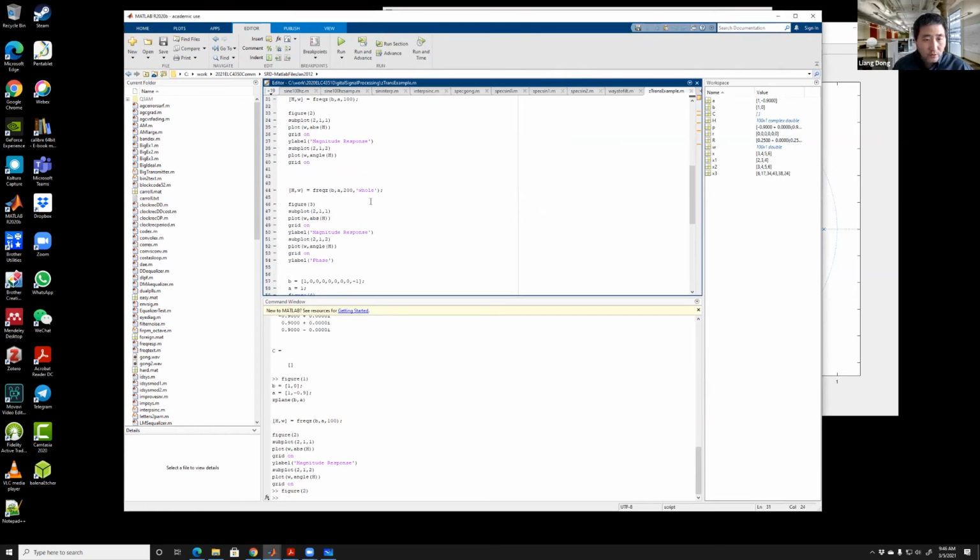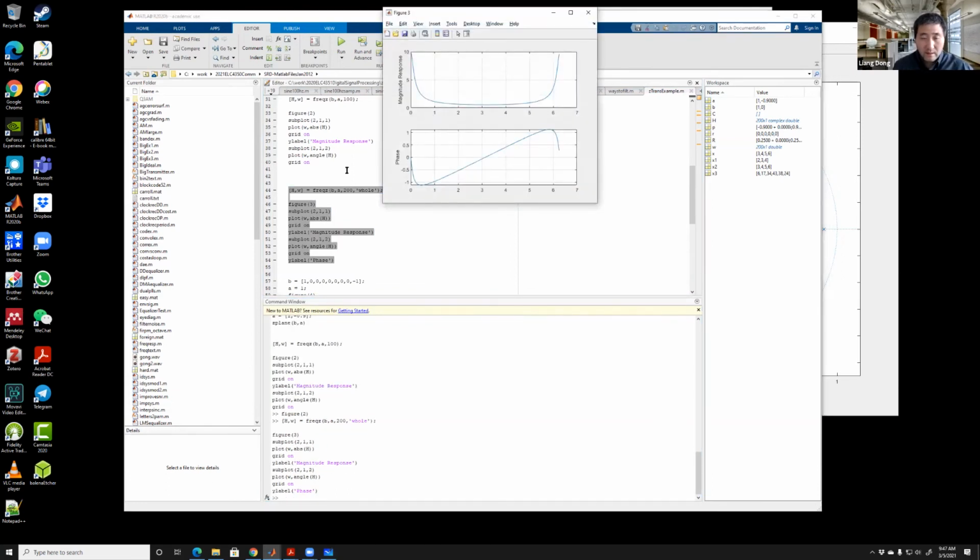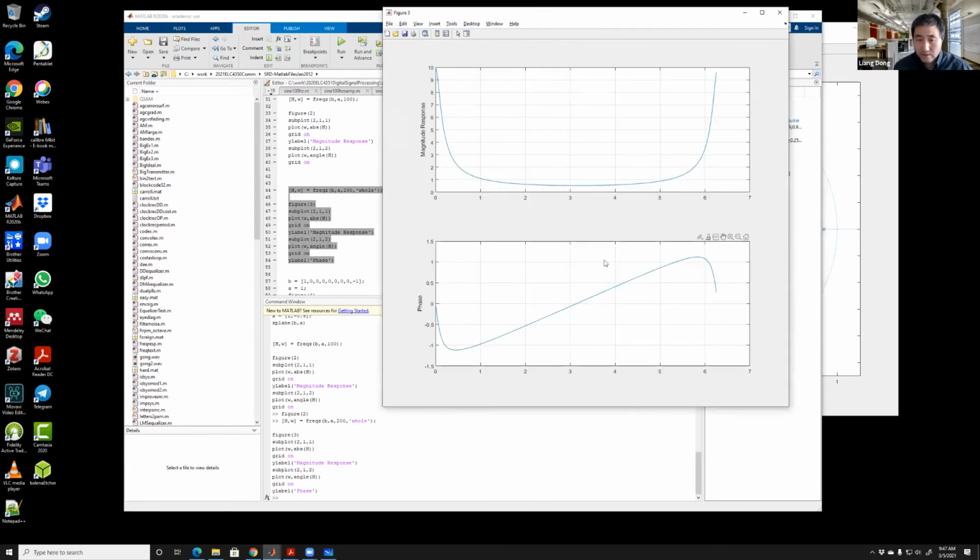Now, if I'm going to draw the frequency spectrum of the entire range from 0 to 2 pi, what you can write is that I want a whole spectrum, and I'm plotting 200 points, and I draw this. So let's see. It's all the same here, but the only thing is I'm going to use 200 points. It's from 0 to fs, the sampling frequency, or from 0 to 2 pi.